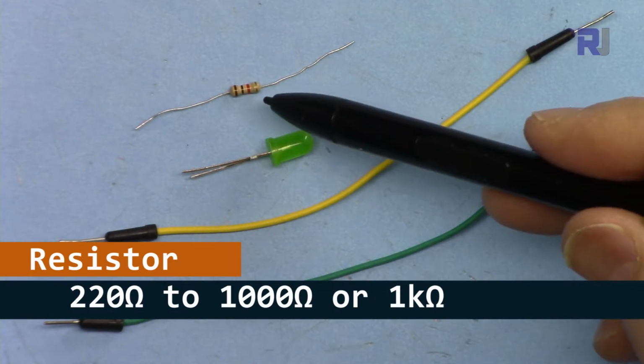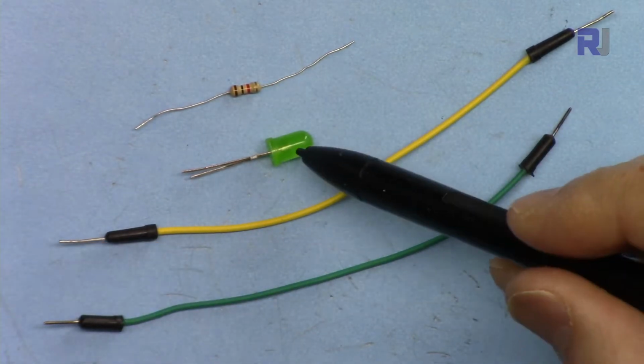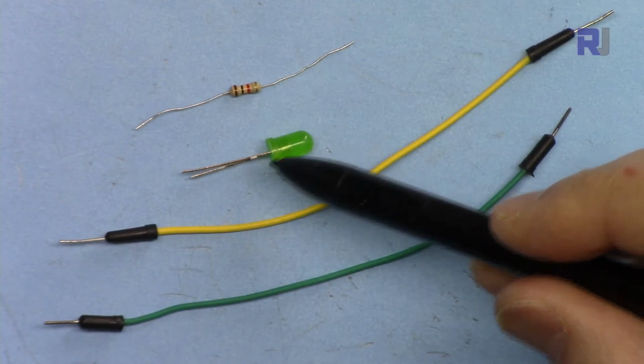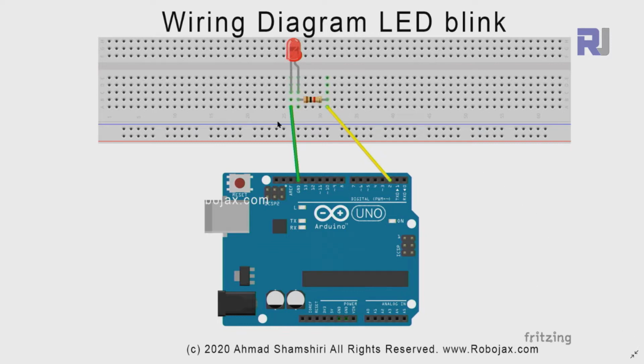For this project you need a resistor, 220 ohm to 1 kilo ohm. You need an LED. You need 2 wires. Here's the wiring diagram for LED blink. I've inserted an LED to the 2 pins of the breadboard. This is the anode, or longer pin.